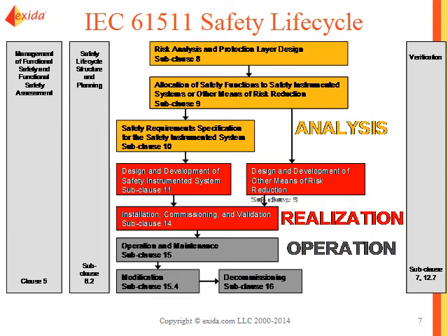If it's another means of risk reduction, which could be, for example, an alarm or a relief valve, the standard doesn't really address that in any detail. So we have a design for other means of risk reduction that's addressed, but not really in the level of detail that we have for safety instrumented functions. Installation, commissioning, and validation, operation, maintenance, and then eventually modification and decommissioning. Throughout the life cycle, we have verification activities. We have an overall life cycle structure and planning in place, as well as functional safety management to ensure that functional safety is maintained throughout the life of the system.